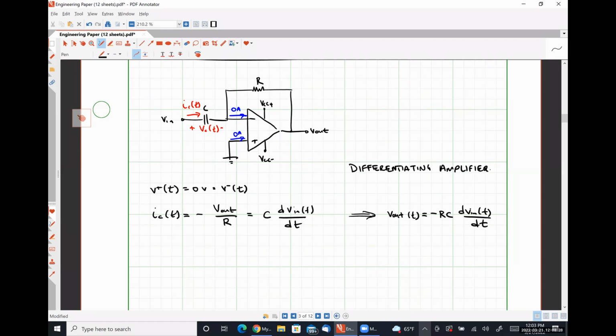Bradley: So does an integrated circuit mean that it's like flat fit on a chip? Exactly. So an integrated circuit means that everything is monolithically integrated on a single substrate, typically silicon. So instead of a discrete resistor that you would go buy from a store, the designer has the opportunity to set aside certain areas of the chip, dope them in certain ways so that they behave like resistors.